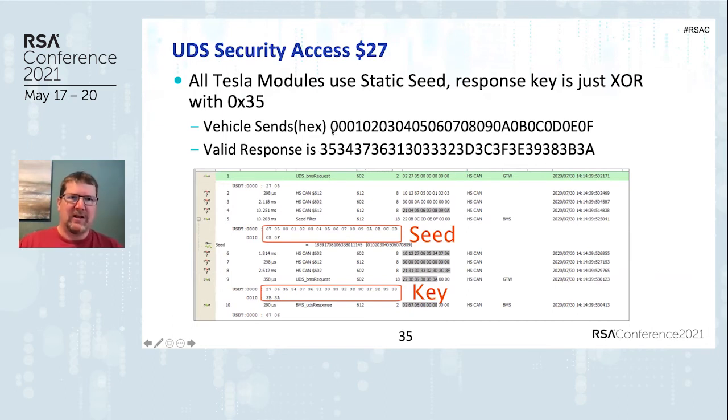So even the seed itself doesn't change. It's the same from every single vehicle, every single module, throughout all the different firmware versions. It's all static. It's basically the only thing that you could really do that would be less secure is just to not use security access at all. It's a completely static seeding key, or basically like having a static password on this thing.